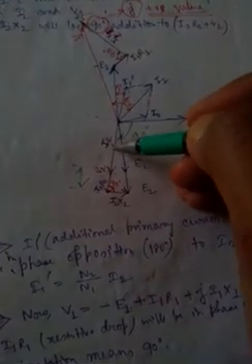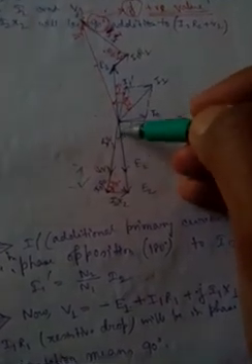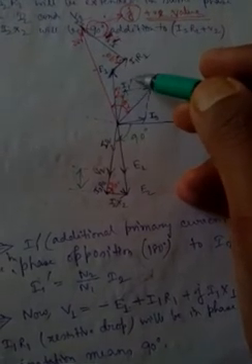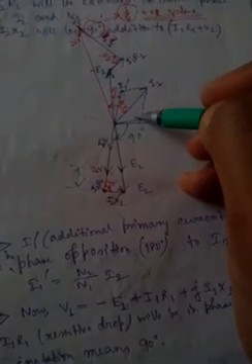So there is a fraction, right? If N2 is greater than N1, then automatically I1 dash is bigger than I2. So let N2 be greater than N1. If this length is I2, then in 180 degree phase opposition we have I1 dash. Now the parallelogram of I1 dash and the no load current is nothing but I1.